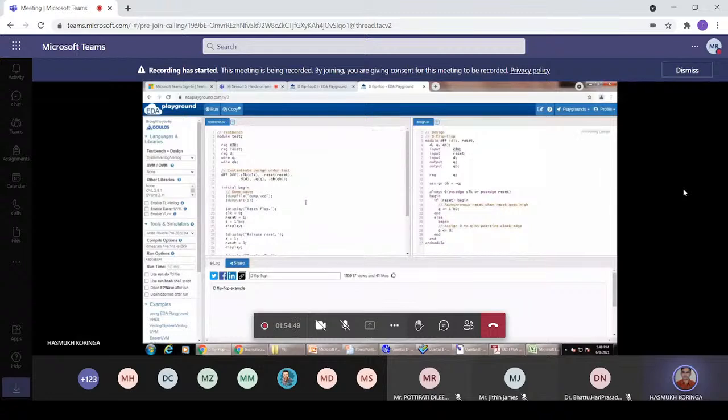Okay. So here one initial begin, and then these dump directives, dump file and dump variables, are used to display the data in the waveforms. So these two are used to display on the waveforms, and this $display is similar to printf in C, to display anything. Whatever you want to display, we have to write in brackets inside two inverted commas.